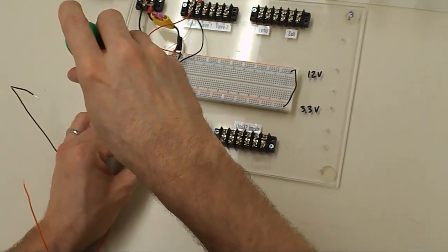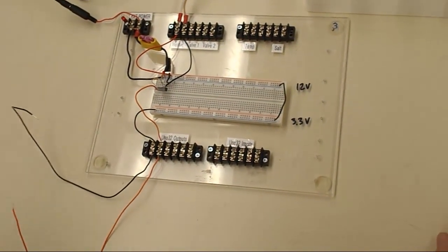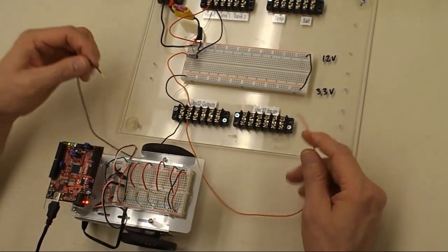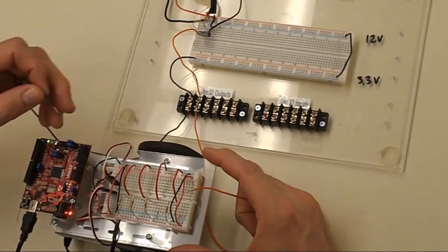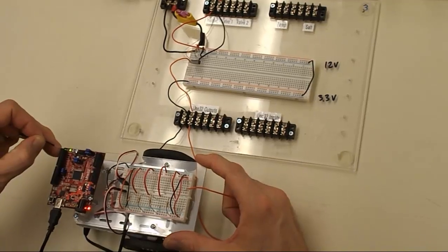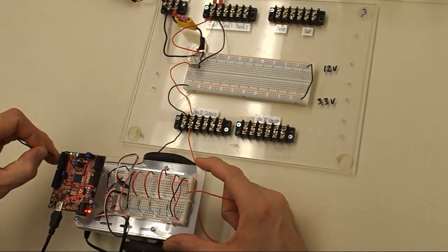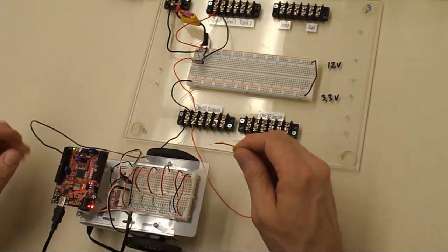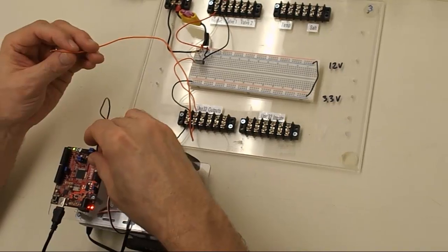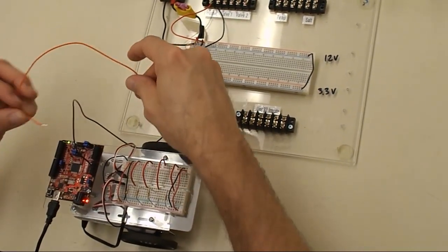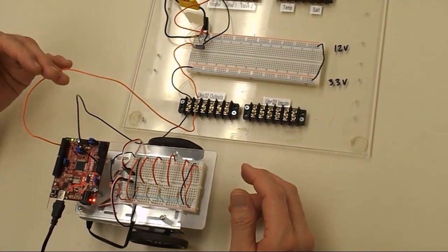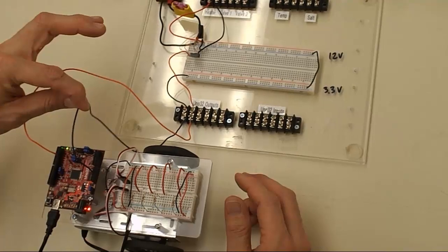And so I've put the program that was provided for you for basic operation into this Uno32. And again, the program you're provided has the heater on digital output pin 3, and so following the labeling down the side here, pin 3 is actually the 4th one up on this side. And, oops, plug that into ground. Careful about that. Ground, where we've been using it last week, and then digital output pin 3 is the 4th one up. And so I'm using colored ones for the digital controls and black for ground.